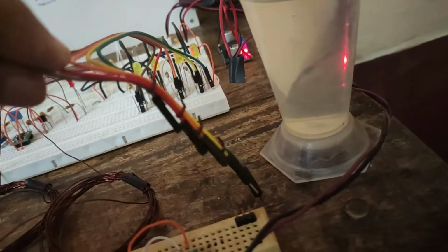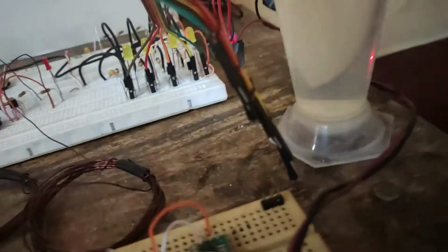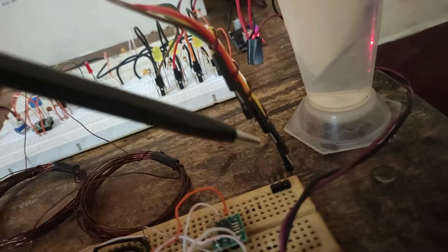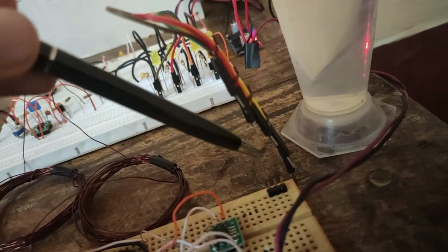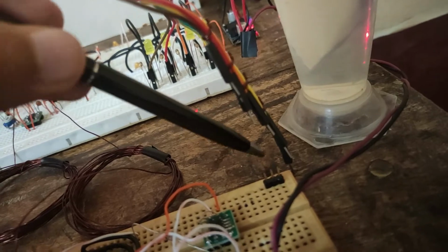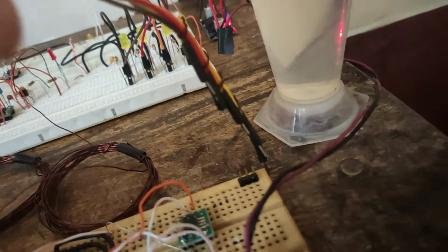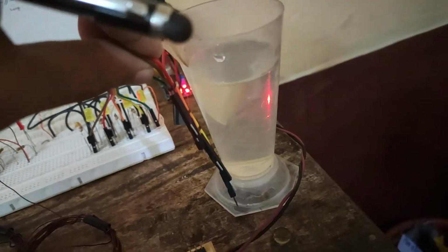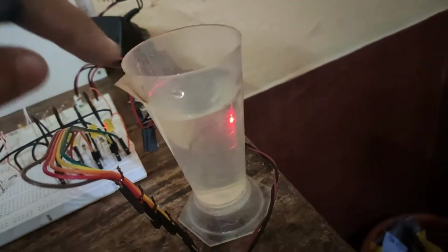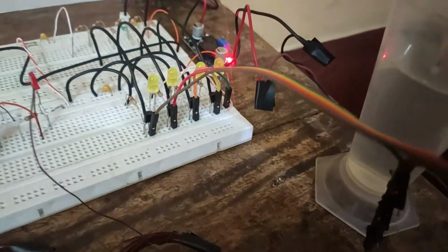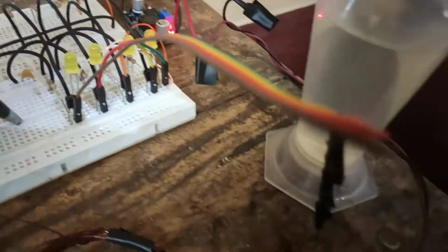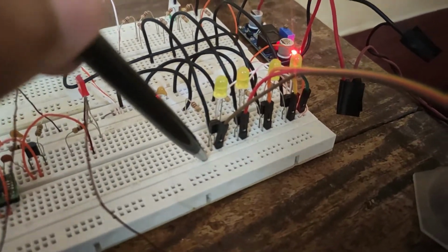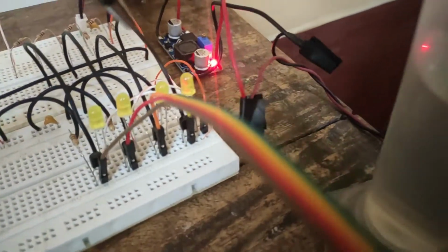So I have taken these jumper wires and tied them up this way to create electrodes. This is L1, L2, L3 and L4, and the bottom one is the reference, which is equal to VCC. This one would go right into the tank this way. Assume this to be a tank. Meanwhile, all these electrodes are pulled from the base of this BC557